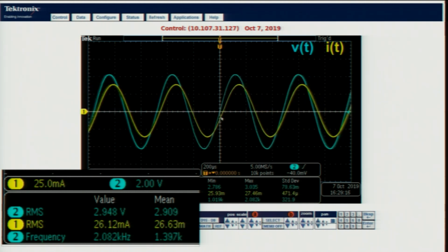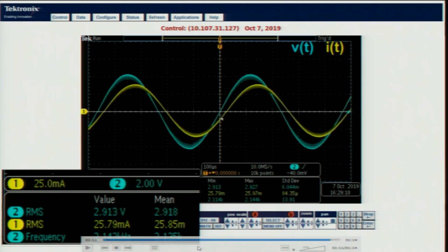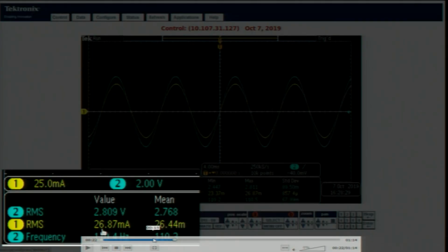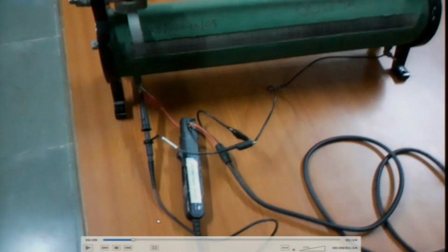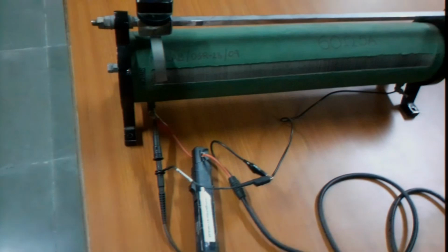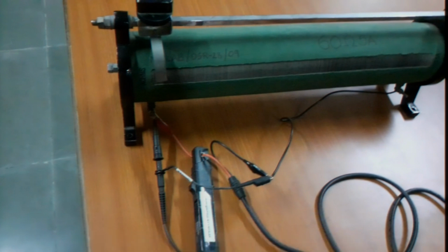If you look at the beginning of this video, can we go back to the beginning of the video? Somewhere right in the beginning where we show the rheostat. Yeah. A rheostat is of course made out of wound wire, and this in fact has an inductive effect. It is almost like a solenoid, but the resistive effect is predominant. The inductive effect starts becoming apparent only at higher frequencies.